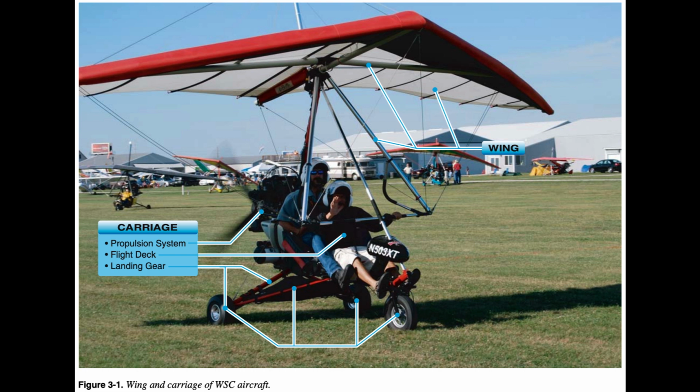Wing. The wing has a structural frame that the sail fits over. Although the wing structure is rigid, it is designed to move and allow the sail to flex and the wing to deform or warp, to provide a simple control system with no pulleys, push rods, hinges, control cables, or separate control surfaces. This simplifies maintenance and reduces the cost and weight of the wing.